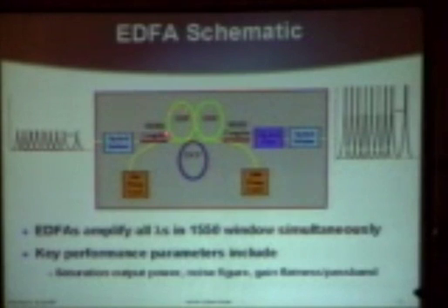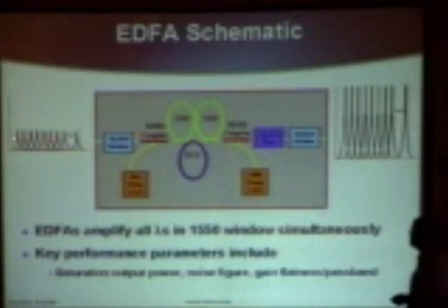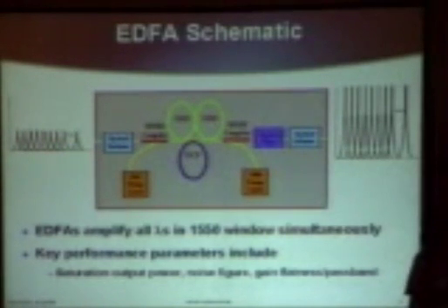There's a special fiber, the erbium doped fiber, hence the erbium doped fiber amplifier, that has an erbium atom added to it. And without getting into the physics, if you pump it with light, the erbium atoms get excited, and when the signal goes through, they amplify the signal. They give the amplification of the signal. So we have a very simple device now that is bit rate independent, and as long as your wavelengths are within the passband of the EDFA, it's channel count independent to a great extent too.